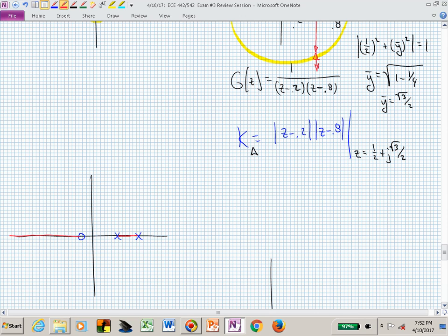And if we just had to quickly sketch this, we would say, oh, this is a circle. The center of that circle is at the 0 location, and the radius is the geometric mean of the distance between the 0 and the first pole and the 0 and the second pole. If I put some numbers to this, what if this happened to be 1/2 and this is 1, or 2 over 2, and let me call this Z1.